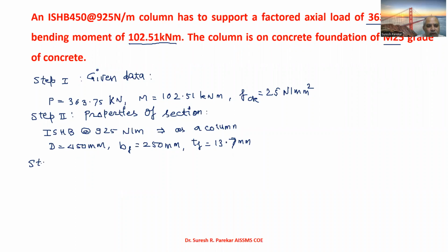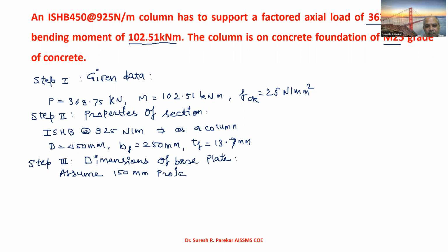Then we have step 3, dimensions of base plate. We go a little bit to the higher side for projections. So assume 150 mm projections beyond the face of the column.